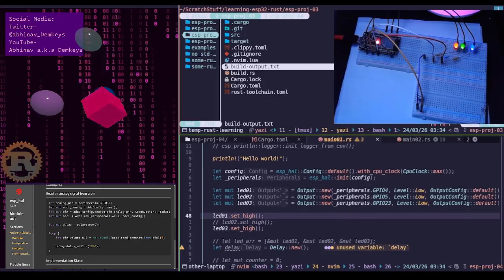Okay? If you change the ratio of those two resistors, the voltage in the middle shifts up or down. So to calculate that, we use Vin multiplied by R2 divided by R1 plus R2.